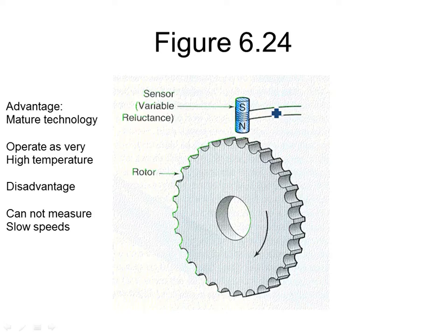The speedometer had a set of magnets that had one on the pointer up against a calibrated spring, and then it had these other set of magnets out here that spun with your tires. And what would happen is when those things pull by, it would try to do what? It would try to pull this other one, but a calibrated spring actually sets your speedometer. And now we don't have that anymore. If you take a car apart now and look at the speedometer, you're not going to see a cable coming up to it. You're going to see a what? My Honda Shadow used one of those cables, and the little gear assembly out there broke.